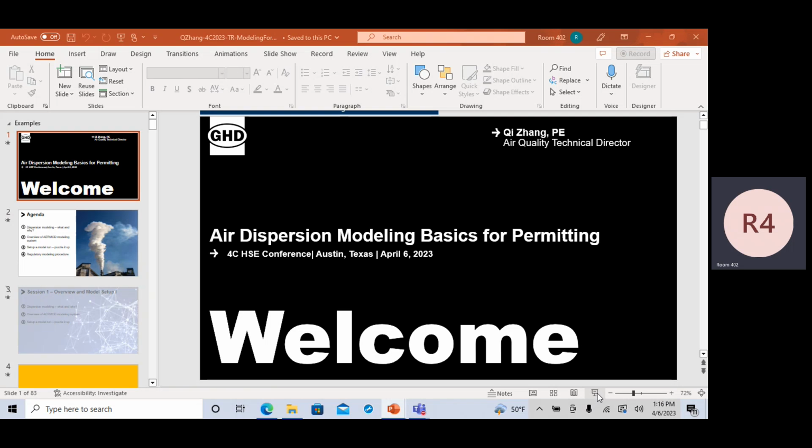They'll give you a box to enter your title of the run, and model options will be just a checkbox whether I want default or not default, and an averaging time, pollutant ID, and run or not run. Run or not run is not very commonly seen in the user interface, but it basically tells you, okay, run the model, click the button, or I don't want to run the model, but I want to verify if my input file is valid.